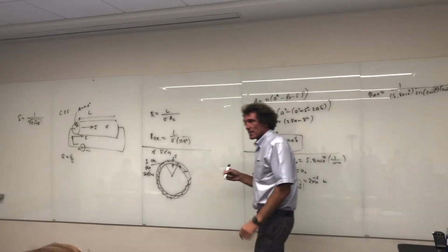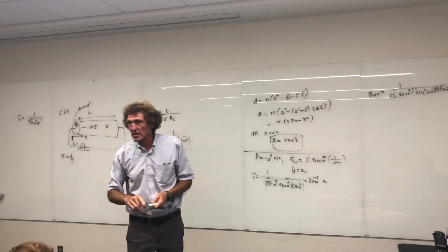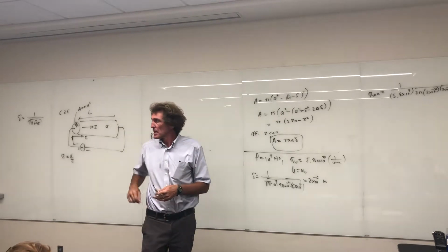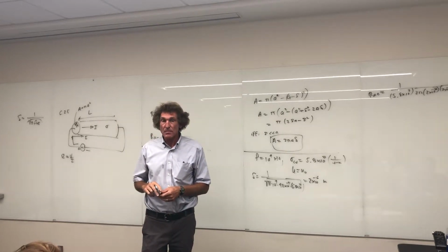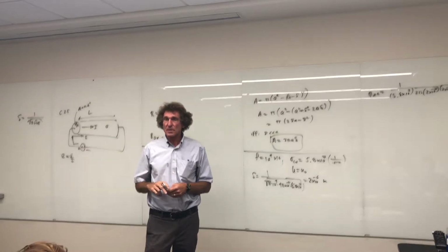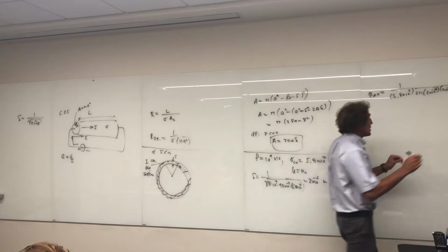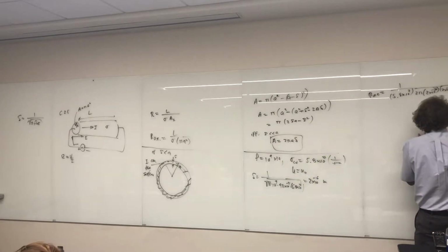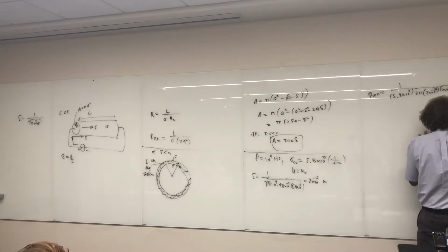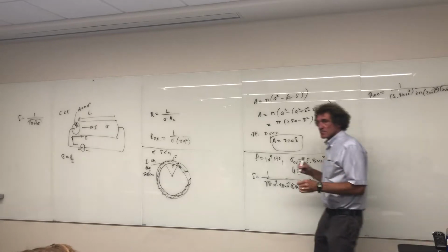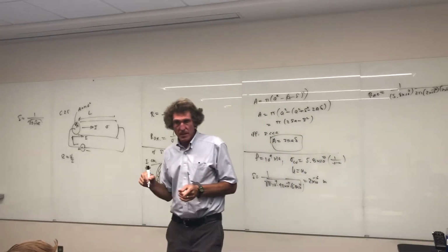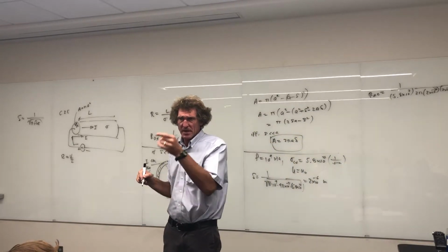Could somebody do that? I don't always trust the book. There are wrong answers occasionally. What'd you get for that? 0.66, what I got. Is that what's in the solutions manual? 0.66? All right, so it's 0.66 ohms per meter. That's how you get the AC resistance. What else do they have for that problem? Is that it?